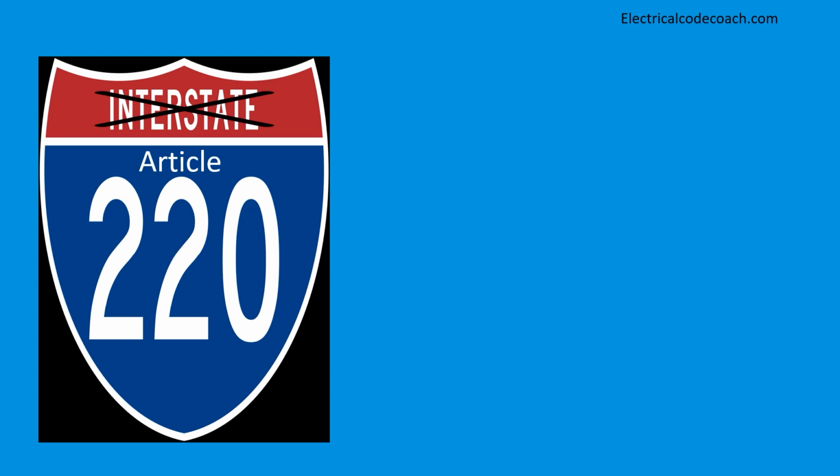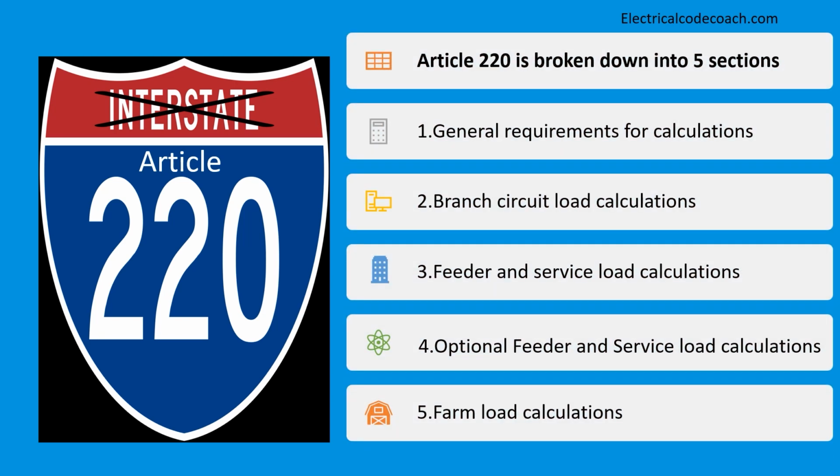So we're going to find ourselves in Article 220. Article 220 is broken down into 5 sections. 1 is general requirements for calculations. 2 is branch circuit load calculations. 3 is feeder and service load calculations. 4 is the optional feeder and service load calculations, and you're going to understand what that means here in a few weeks. And 5 is farm load calculations.